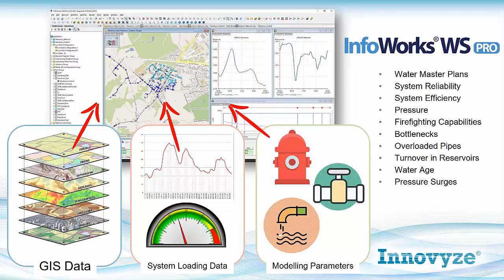Most of the time, hydraulic models are used to create a water master plan, or to find a method to improve the system reliability and efficiency by evaluating existing or future configurations of the network. The model can then be used for a wide variety of uses, like identifying pressure, providing firefighting capability, identifying bottlenecks, overloaded pipes, turnover of reservoirs, or doing water quality analysis, identifying water age, or transient analysis to identify pressure surge.